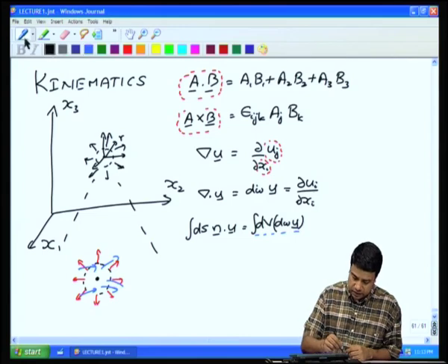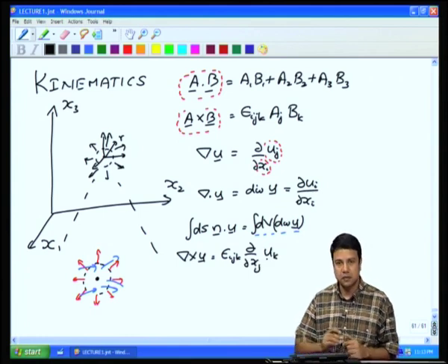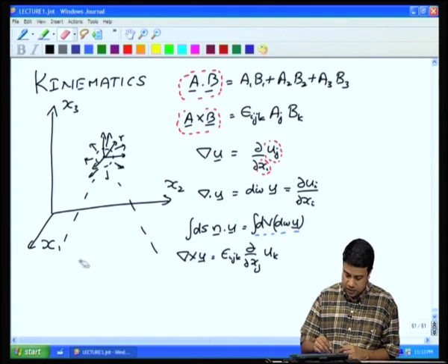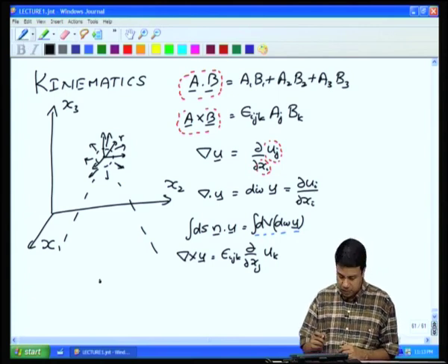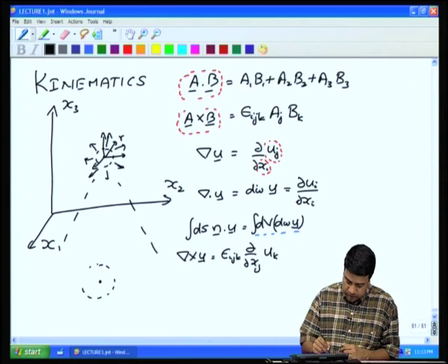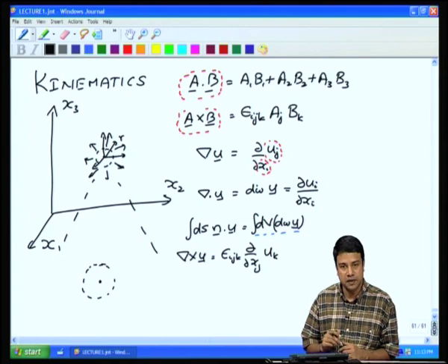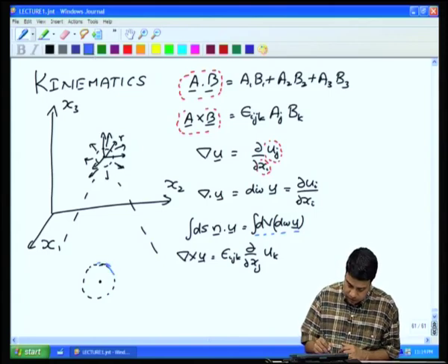And the other vector that we had defined was the curl del cross u, which is epsilon i j k partial by partial x j of u k, the velocity. Okay, that is the curl of the velocity vector. Okay. And in the last lecture, I had shown you in a simple example that this curl of this velocity vector, okay, over some curve, over some line in this 3-dimensional space will be non-zero only if there is circulation around this point.